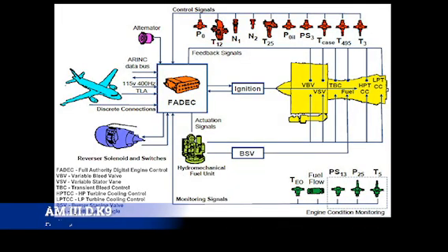Finally, let's look at FADEC one more time. The full authority digital engine control. Okay, so FADEC, it's an electronic system that controls all aspects of the engine's aircraft performance, commonly used in most of your 737s. All your modern jets use FADEC these days. Now, it's a digital computer system that fully manages the entire operation of the engine, including fuel flow, thrust settings, critical parameters. It replaces all mechanical or manual control inputs.